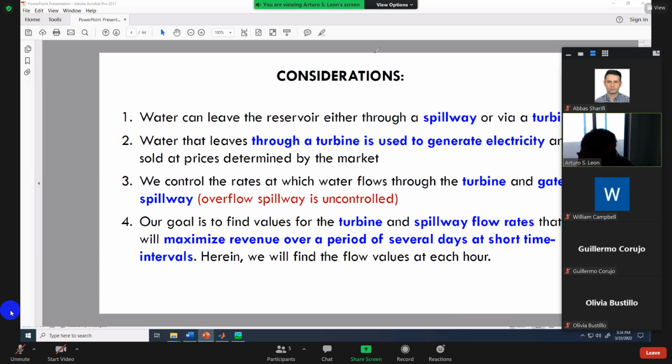So probably what the U.S. Army would do is, okay, we have a problem downstream, we have an obstacle. If we release water, we are going to produce floods. So they will shut down the gates and release only a little amount of water to prevent flooding. At that moment, we don't rely on the computer model anymore. At that time, we rely on the engineers that are in charge of the system. I'm not sure if that makes sense, William.